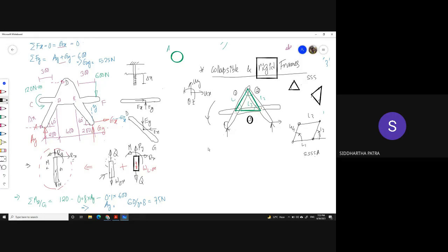But again, you might be confused with the fact that the roller only prevents the structure from going in the downward direction at A, not in an upward direction. But you see that the design is only based on the fact that if this body has a tendency of rotation, that will only try to bring A in the downward direction. That's why the support is only provided from the bottom, and it is only preventing the motion in the downward direction. So in essence, the purpose of A is to prevent the rotation.